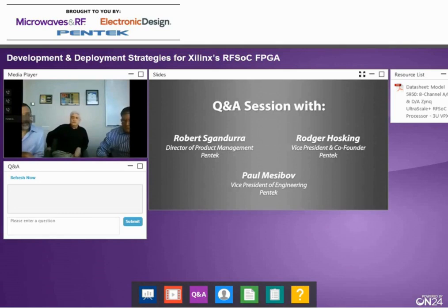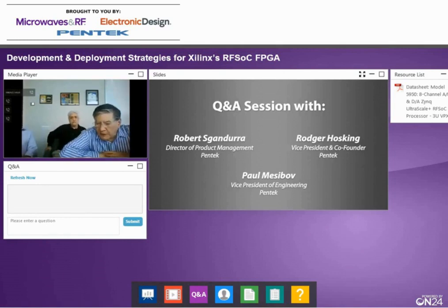Thank you. Our next question is, what is the maximum decimation for the DDCs? I'll take that. Following up on Paul's last answer, inside the RFSoC chip itself, the decimation is by 2, by 4, or by 8. But in the FPGA fabric of the RFSoC, we have implemented an additional by 16 decimation to get you a decimation all the way up to 128.